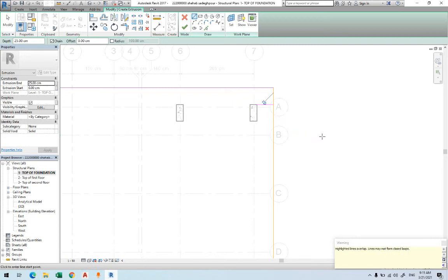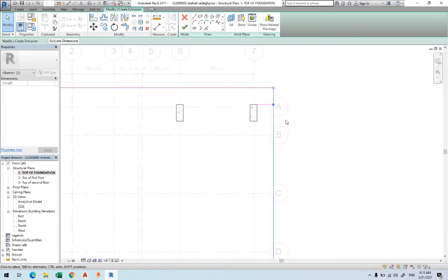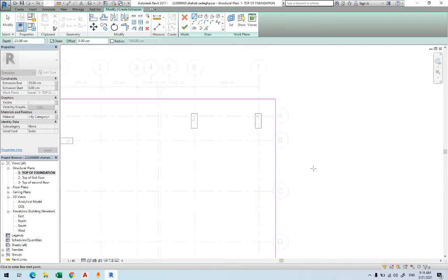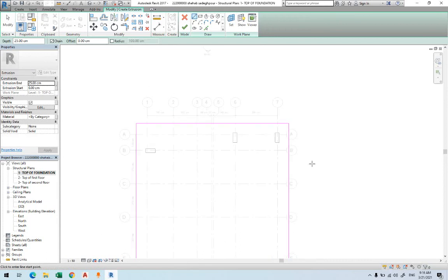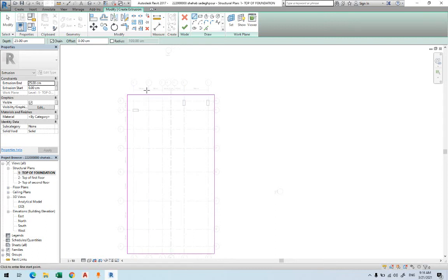Well, I can press escape, and then I can delete what I have there in order not to have any overlap. I'm deleting those, and I already have the starting point. So I'll draw another line from here down, which is 17,750. Now if I press escape, one escape is okay, you're still in drawing mode. So in this way, I have a closed area.